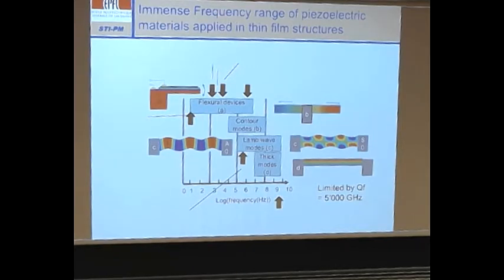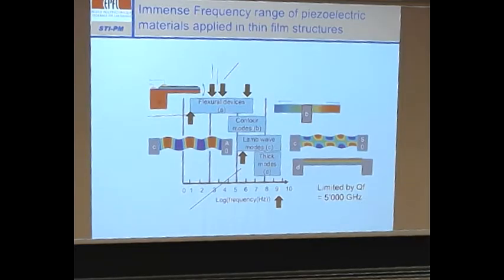You put a piezoelectric film on some membrane, cantilever, beam or bridge, and it's deflecting. It cannot be too big, though. Downscaling always means that the frequencies go up, so when you make something very small, you cannot at the same time make it very slow. But you can go down to at least 100 hertz.